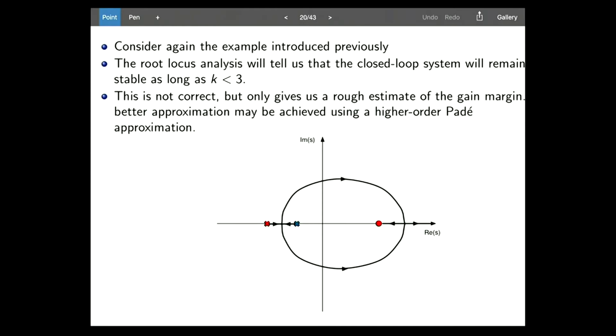I hear a lot of buzz. The question concerns the rule for sketching root locus, which tells us that the root locus is on the real axis to the left of an odd number of poles and zeros, and here this doesn't seem to matter. Anybody know the answer? Very good, an excellent point. Can you repeat the question?